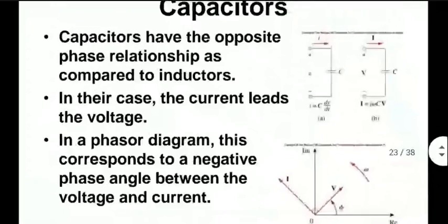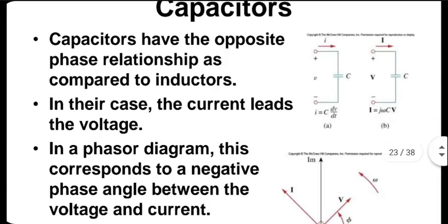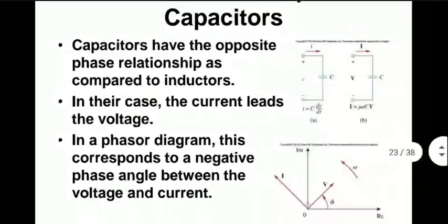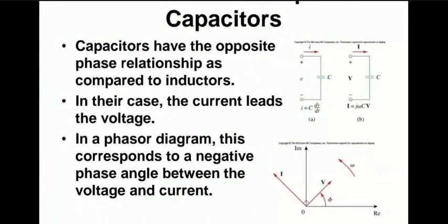By the way, when you mention the power factor of a circuit, generally it is also mentioned along with the value whether current is leading or lagging. If the current leads, we say power factor is leading. That is how industry talks. Leading power factor means current is leading. Lagging power factor means current is lagging. Nobody will mention that current word all the time. They assume that you know. Leading power factor means current is leading the voltage. Lagging power factor means current is lagging the voltage.